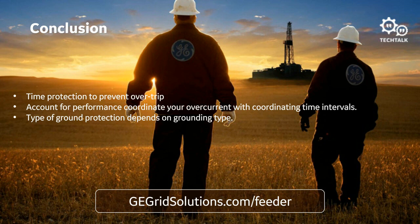Negative sequence is a little bit more complicated, because typically with negative sequence, what you want to do is trip for something like an open phase or a loose conductor or things of that nature. So the challenge there is you always want to set that large enough that you're not going to misoperate because of CT accuracy issues, but you want to set it small enough that you can catch those sorts of conditions.